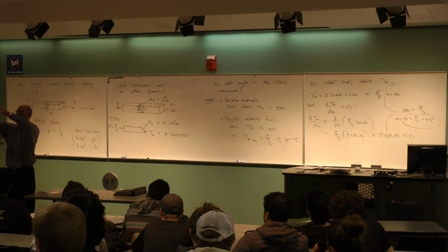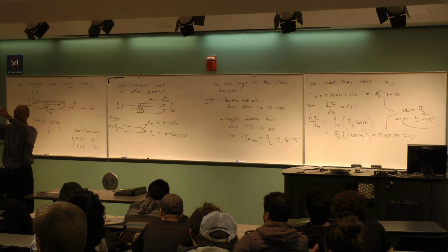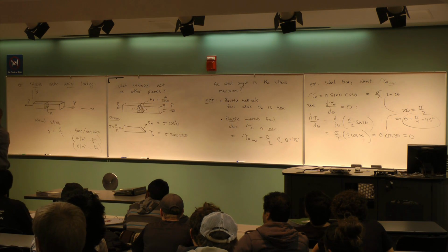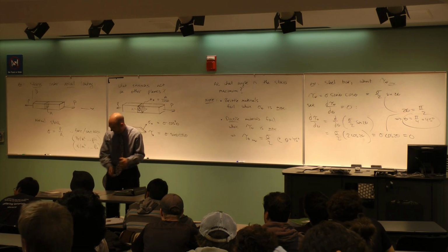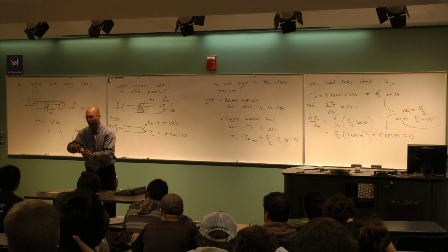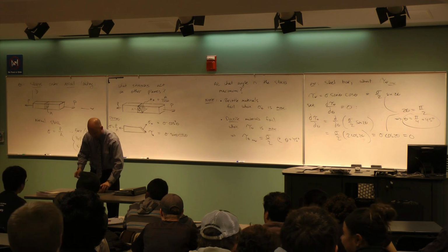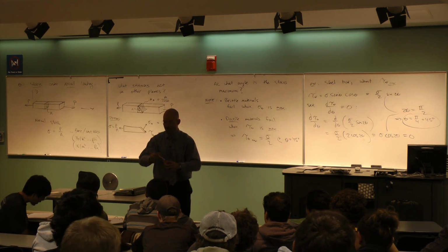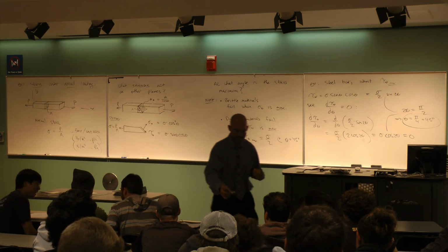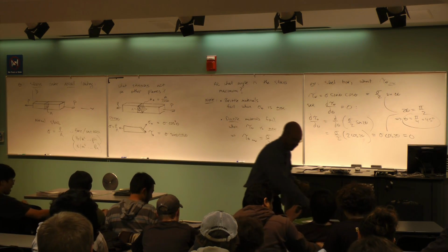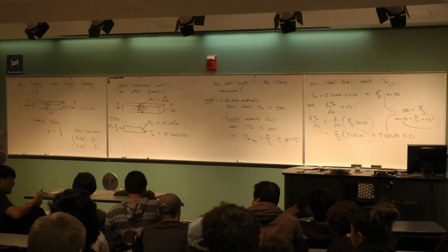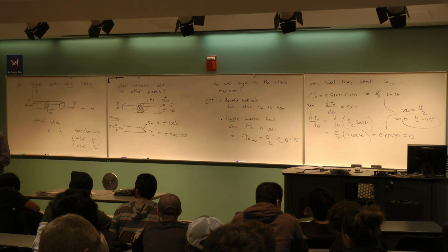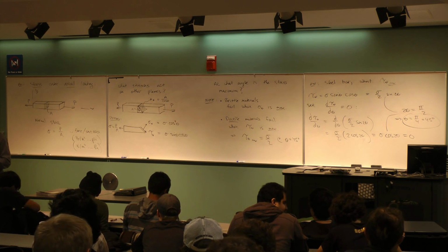Okay, here's what happens when you twist something that's brittle until it breaks, right? Take a look at this. Can we see? Does that thing break straight across? It breaks at what angle? It's a helix. By the way, I got a whole thing of chalk here. Anybody that wants to break some chalk here, please. But you want to break it by twisting the chalk. You might want to put a little nick in it. Anybody you want one? Break some chalk. Bring the broken chalk with you. The point is chalk is what kind of material? Ductile or brittle? Brittle, but I'm not pulling it. I'm twisting it. So I'm changing the problem.